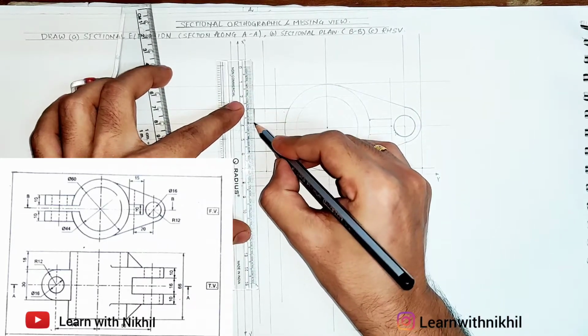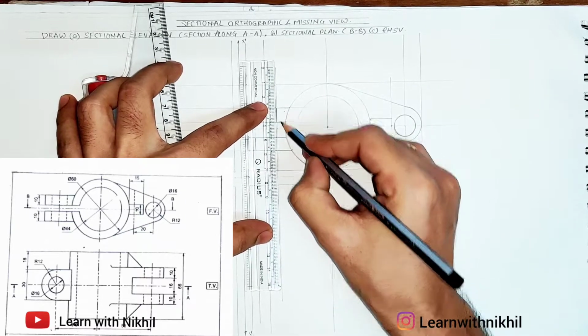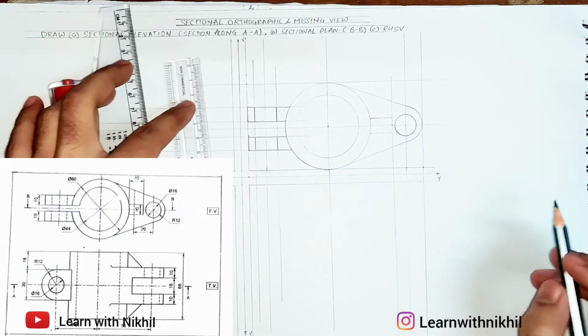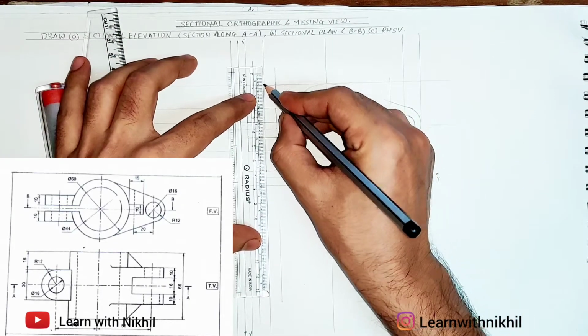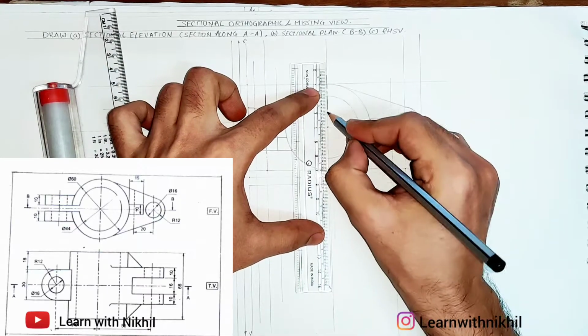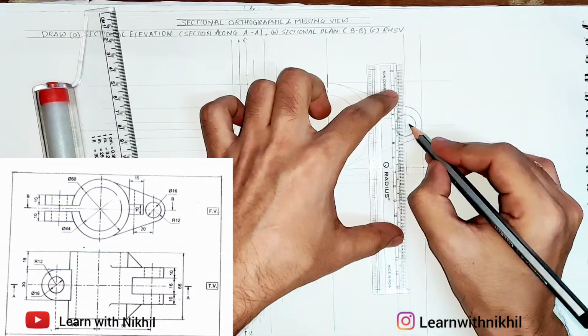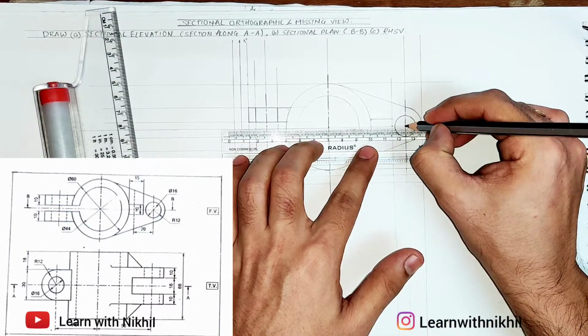Now this part, in the question you can see it is dotted hidden, but after the section this part will be visible, so I'll draw it dark. Now draw the center line wherever you have the circle or on its projection, that is big gap, small line, gap, big line.